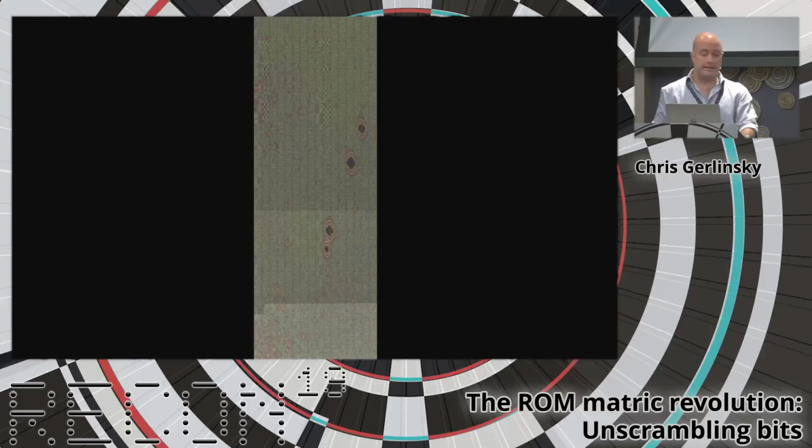Now this is an ST19K7. This is the entire ROM from one of the chips. There's a little bit of color variation. That's just from starting and stopping the process of taking the photos with the microscope. There's a few holes in it. That's because this chip I delayered using hydrofluoric acid, and with the wet etching process, you don't end up with a totally planar result. So I have some little holes where the acid etched a bit further. In this case, I don't consider it a really big deal.